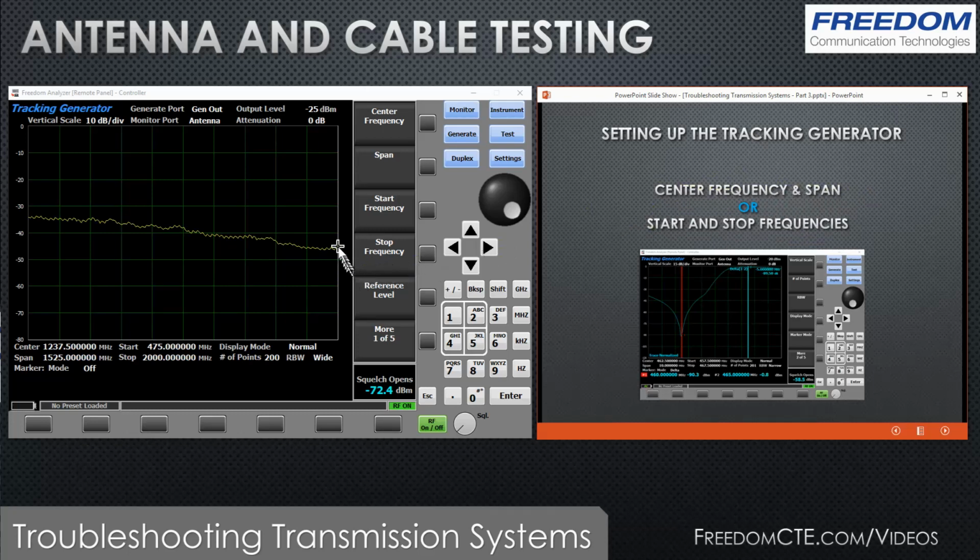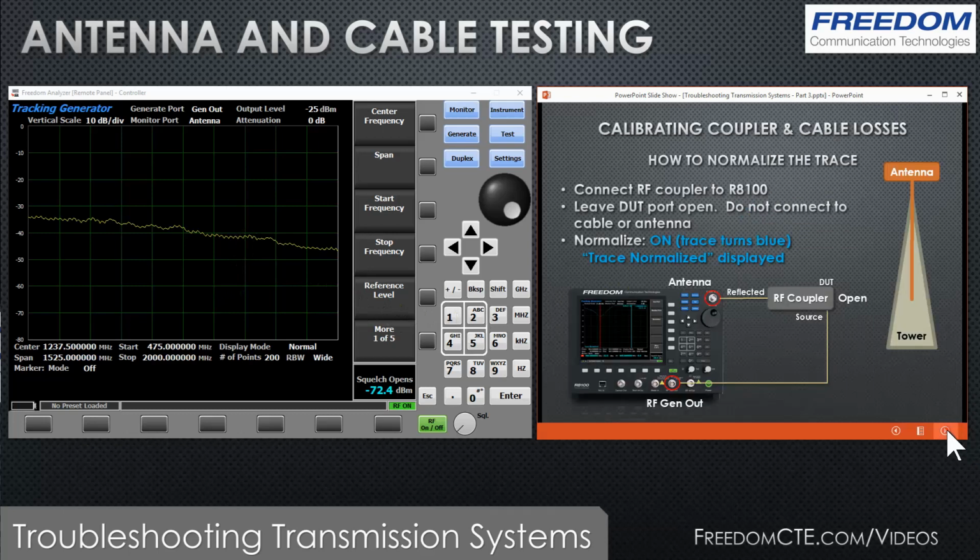Now in this case, I have an antenna that's a 700/800 and GPS, so I've set a fairly broad span. I want to be able to look at the 700, 800 megahertz. I've actually started at 475 megahertz and gone all the way up to 2 gigahertz, since we'll be looking at the 1.3 gigahertz for the GPS. So very, very broad.